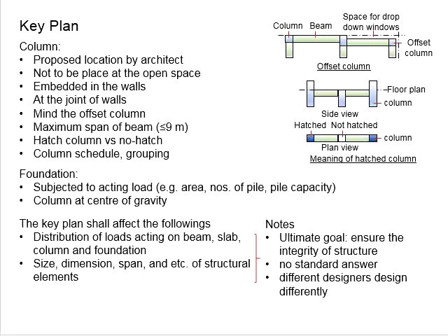In this case, you don't have to design the slab to be a suspended slab. It can be a non-suspended slab, where you only need to provide the minimum reinforcement bars to control the cracking of the slab, and the slab is fully supported by the soil.